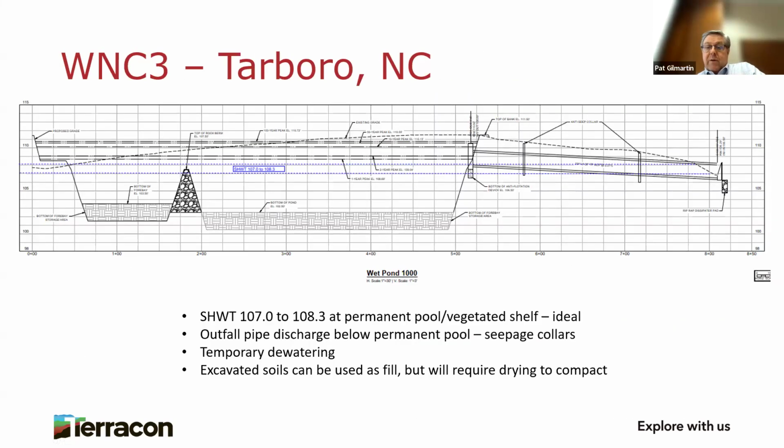Sorry. The other reason that we evaluated the soils, I mean, we're below the seasonal high water table. We wanted to make sure that the soils coming out of that pond, like every site, if we're going to do an excavation, can we reuse those soils for fill? And the answer on this one was, of course, yes, but you're going to have to dry them out, which is pretty much the answer you're going to get on any coastal plain site. You dig below the water table, the soils may be suitable for use, but they may be really wet and difficult to use.